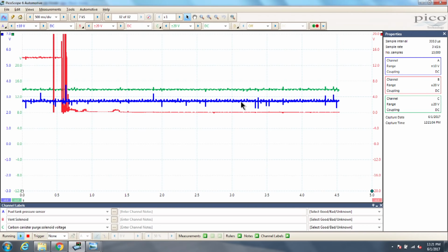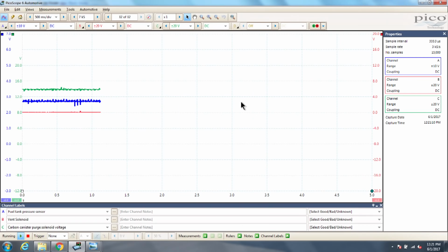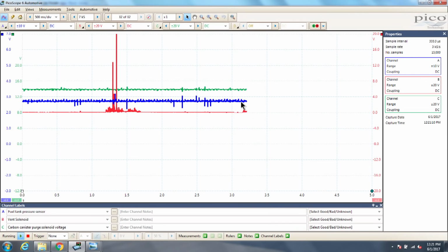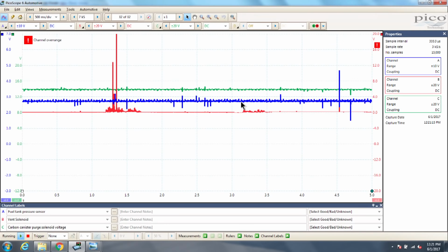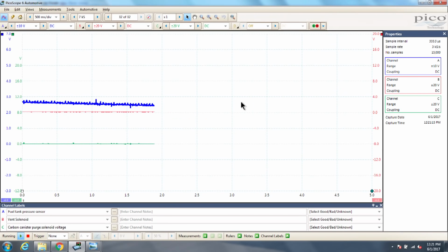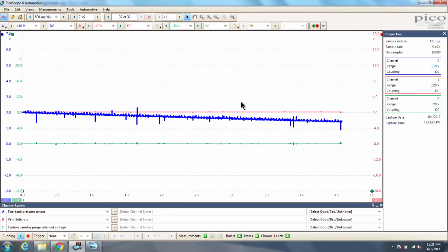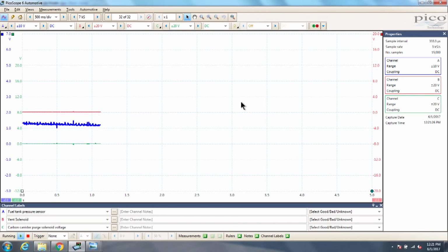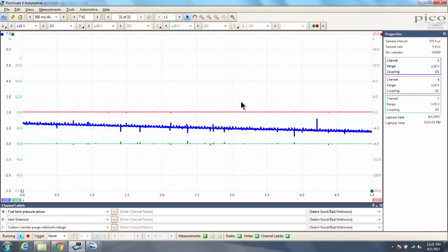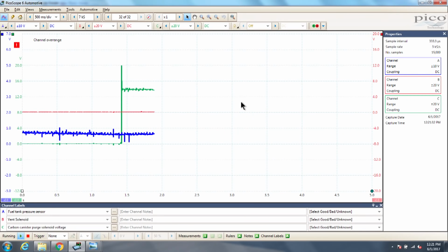The computer is currently not driving the purge solenoid, so I'm going to drive it. I'm going to turn our purge on 100%. And there we go. Our purge is grounded, our vent is grounded. Look at our fuel tank pressure drop. And then at some point here, after I cross that threshold, whatever it may be, I would let off of here. So we'll bring it down just under 1. That looks good. We're under a volt, and I'm going to leave it sit.